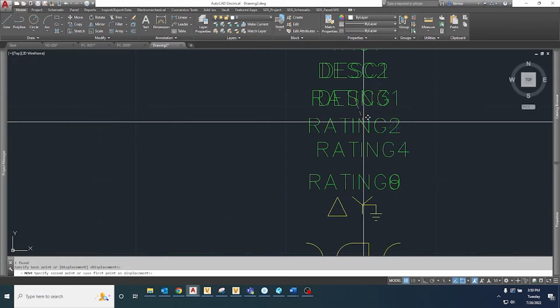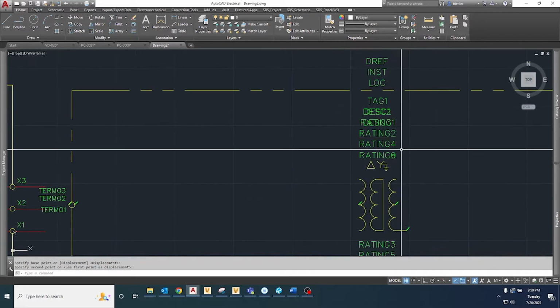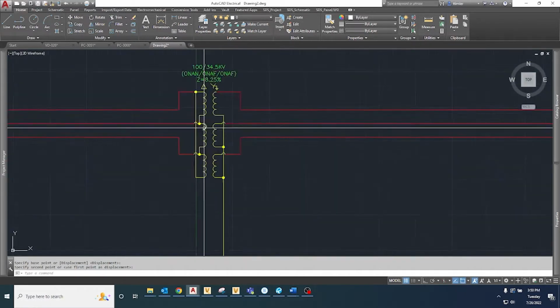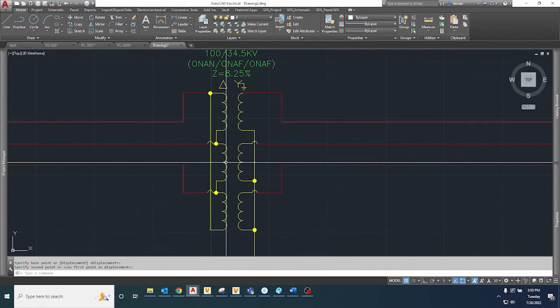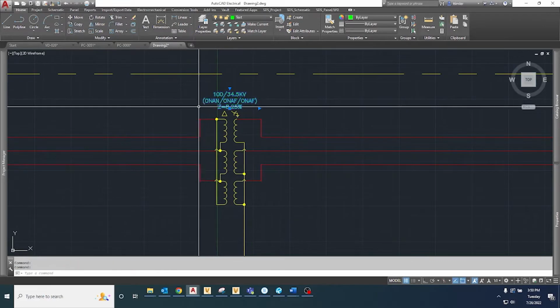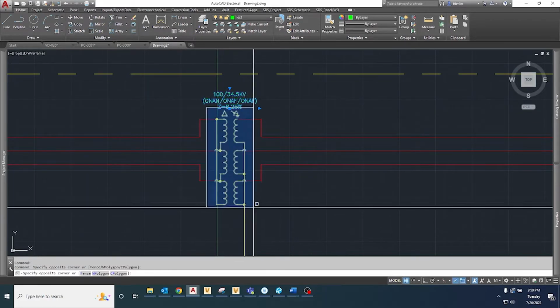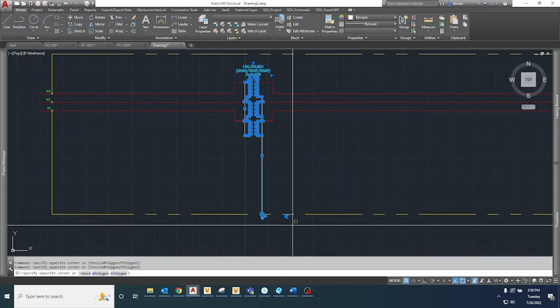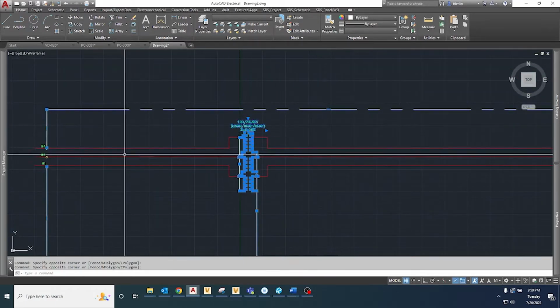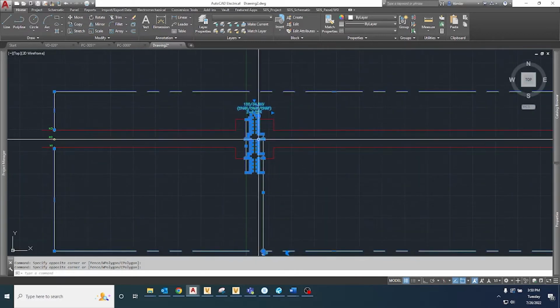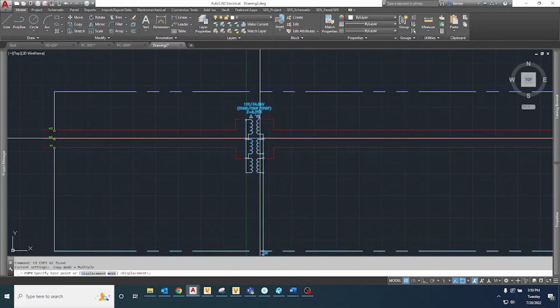Now I want to reposition my geometry so that my insertion point is at the 0,0 origin point, and then work outward from there to arrange the geometry so that the connection point attributes will fall on snap points on my grid. Reworking the symbol geometry is always the most time-consuming part of a symbol build, with or without the AutoCAD Electrical Symbol Builder. Using a grid spacing and snap points is not a requirement in symbol building.